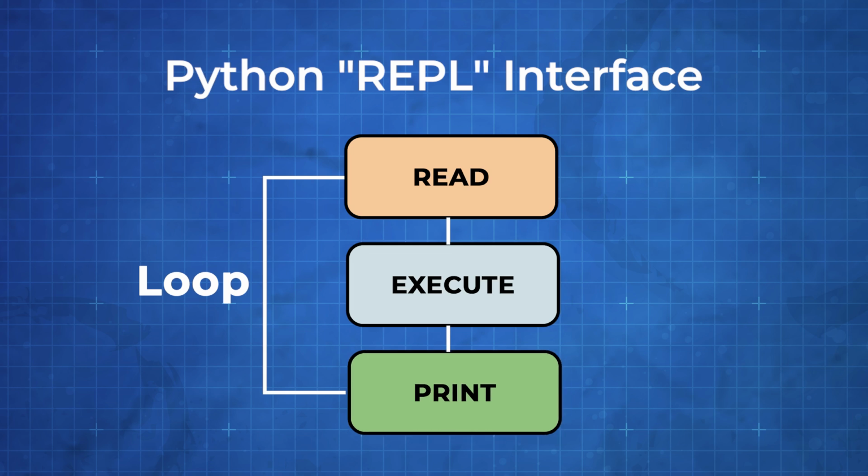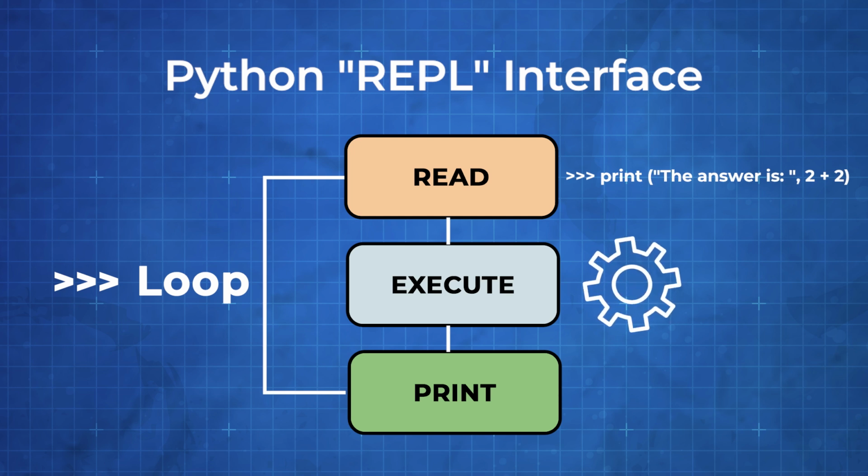When MicroPython is loaded onto an embedded platform, it outputs the REPL over one of its serial interfaces, like UART. We can then connect to it with our computer using a terminal emulator or the MicroPython remote control program, MP-Remote, and interact directly with the REPL on our board. We can use this to test lines of code, navigate the file system on our board, and execute entire scripts.